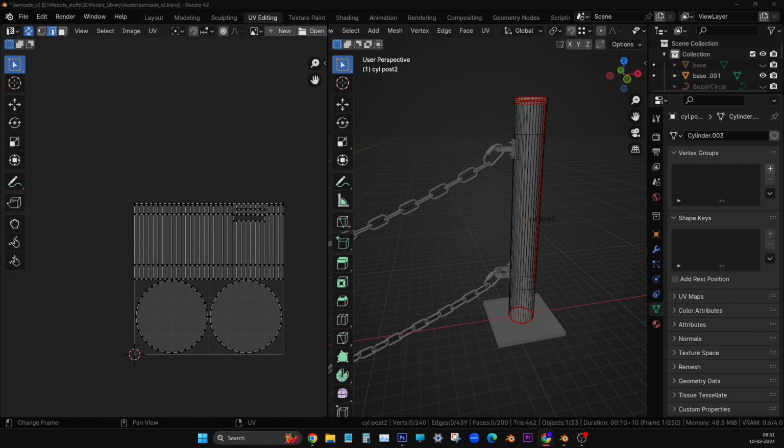Yeah. Okay, I think two edges are there. How come? Okay, just press M on the keyboard. M. By distance you choose. Now go to the settings. No, left side, down side, down right side. Merge by distance option is there. No, whenever you apply a tool, the settings will come. Black color, down. That one. Yeah, increase that to 0.01.